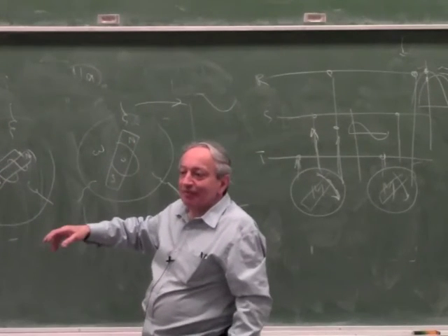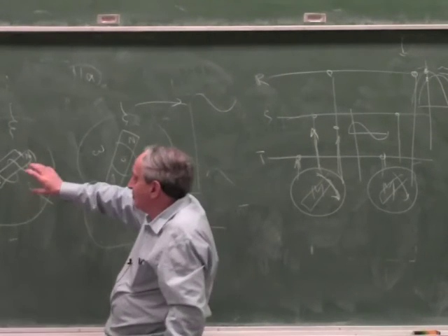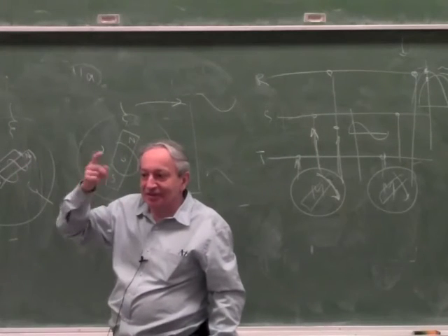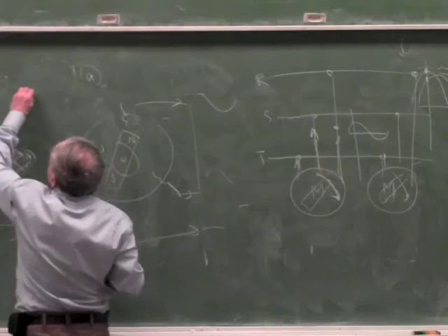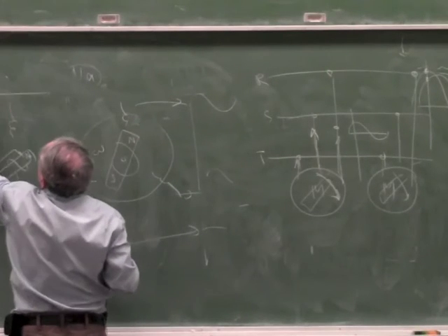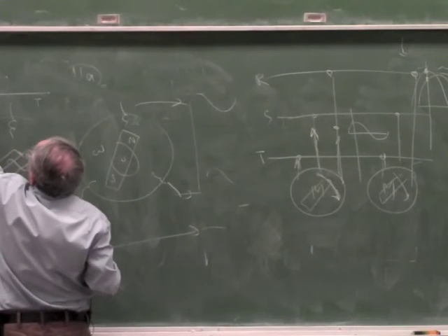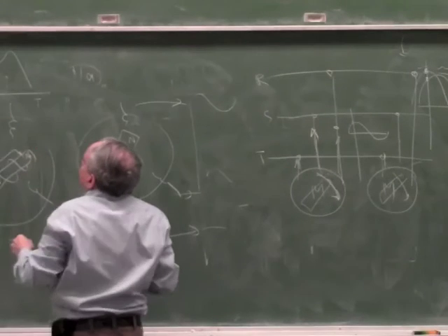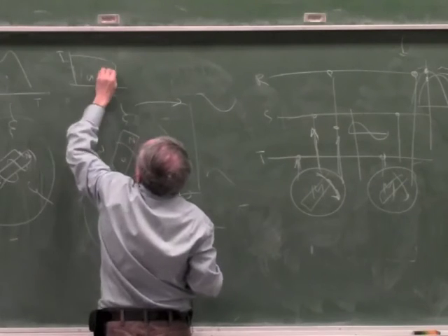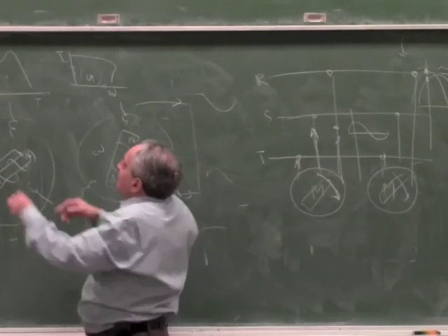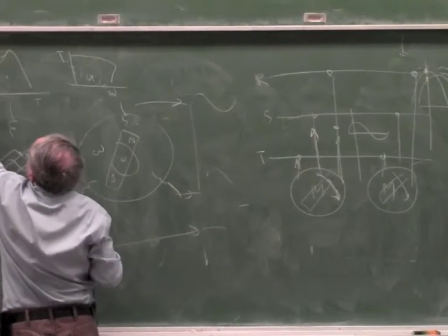So what happens if I take all the load off? If you take all the load off, it will still have to slip a little bit behind the synchronous frequency, because otherwise there will be no induced current. Remember the graph for this thing, if you draw torque and omega, if you draw it in this way, this axis looks like this, or we drew it the other way, torque versus omega, but it's the same graph. So if you take off the load, it's going to sit about here, which is very, very close.